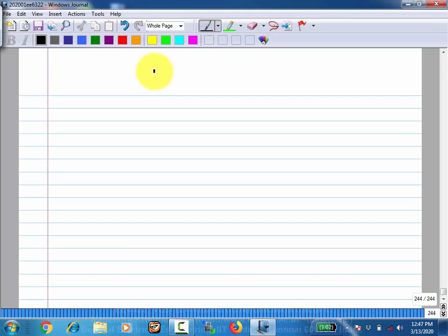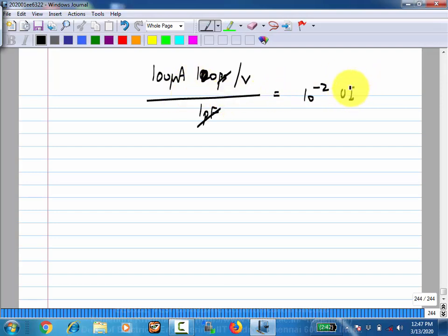ICP is 100 microamperes. KD is 120 picoseconds per volt, and C is 1 picofarad. So how much is this now? Let's make it 100 picoseconds for simplicity. This pico goes away, and then you have 10 to the minus 2. So this multiplied by 2 pi is the phase. This is the unit interval, so 10 to the minus 2 UI.